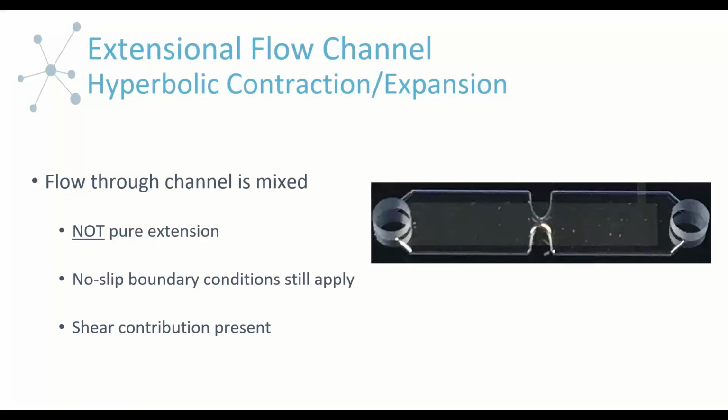I wanted to also point out that we like to be very clear with our technology that this is not a pure extensional type of deformation, because we still have the confines of the flow channel. This means we still have no slip boundary conditions that apply. So that means we're still shearing the fluid. There's still a steady shear being imposed on the fluid as well. So we just like to be very clear that this is a mixed flow situation.